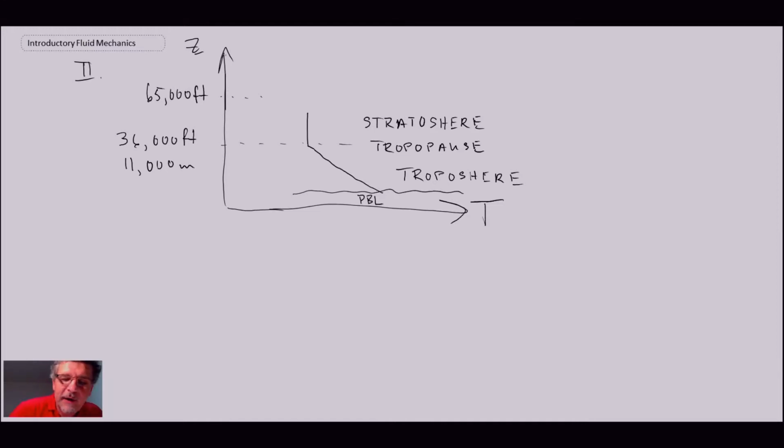Whenever you're flying in an aircraft, the highest you probably get to would be about 45,000 feet, so you'd probably be in this range here. But we have a linear relationship in the troposphere. We get to the tropopause, and then it becomes a constant temperature, typically somewhere around minus 60 degrees C. I think technically it's minus 56 for the standard atmosphere, but it's anything around there.